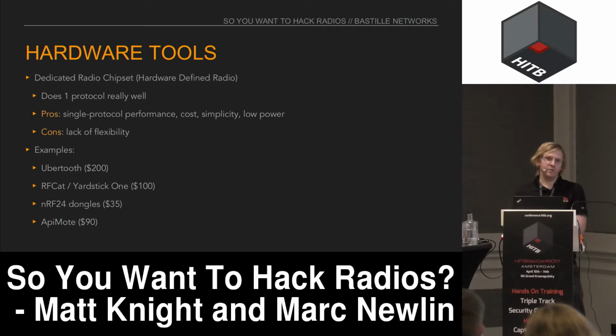So on the radio side, we have the distinction between hardware-defined radio and software-defined radio. A hardware-defined radio would be something like the cellular modem in your phone or the Bluetooth radio in your laptop. And it's an integrated circuit which is designed to do one protocol really well, but it's not good for a lot of reverse engineering processes because you can't configure it in the way that you need to look at an unknown protocol. So we have some devices here for looking at Bluetooth and Nordic NRF24 and sub-gigahertz FSK protocols and Zigbee 802.15.4.